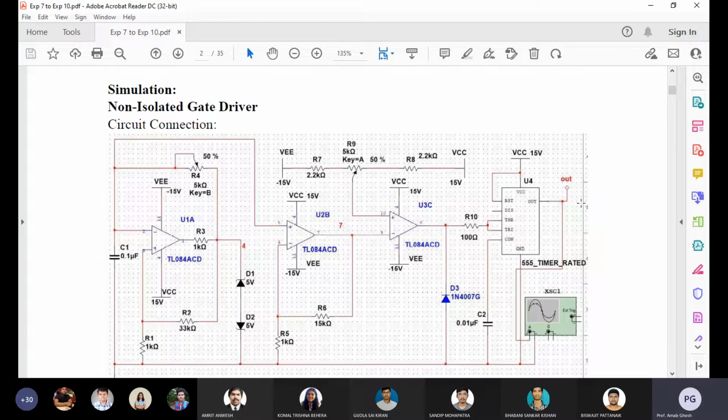Okay, so you have to increase that. Then you can understand if you want to increase the voltage, the error is more, and the pulse width also should be more. On time pulse width, not off time. Only under those conditions can the error be minimized. You have to cross-check it at both ends. So logically, you can understand your gate driver is okay and it can work for those conditions. You are getting my point?